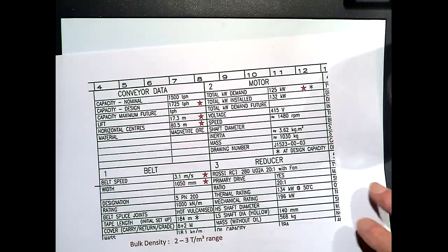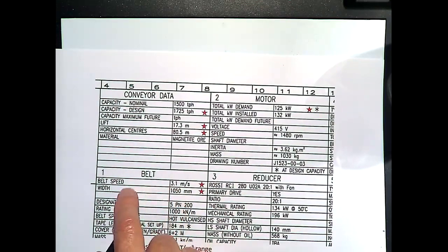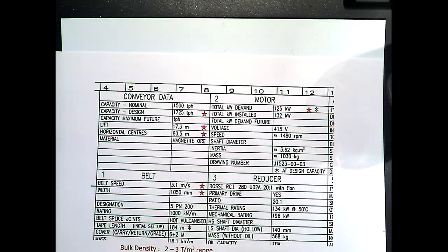Right, okay. The 3.1 came, because it was here a couple of days ago, we looked at it. The 3.1 was their selected belt speed. Now, we realised that it seemed to be a bit faster than what we needed, but remember we were a bit confused because the burden isn't exactly the way it's on our chart, because we didn't have the surcharge. You know, on the photograph that I took, it was fairly flat. Okay? So that's where we got the 3.1.